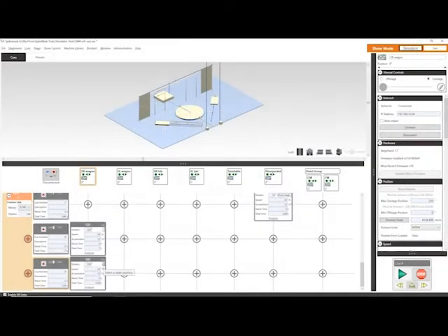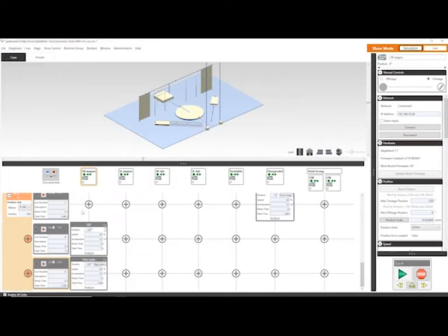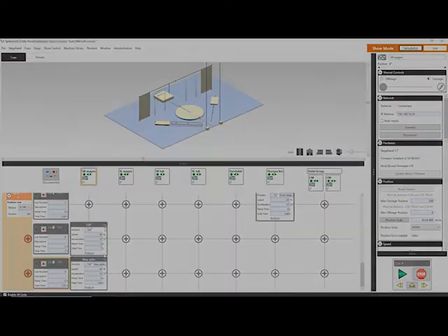Spikes allow you to easily track and adjust positions of the machines throughout the show file. To set a spike, just click on the Spike's Position button, click the plus sign, select the spike, and click OK. Changing a spike position is just as straightforward as setting a spike. Open the Spike dialog box, change the desired spike, and click OK. Now all movements are updated with the new spike position.